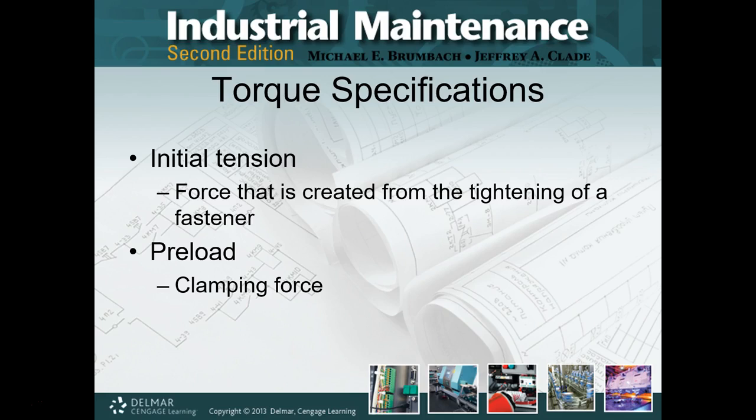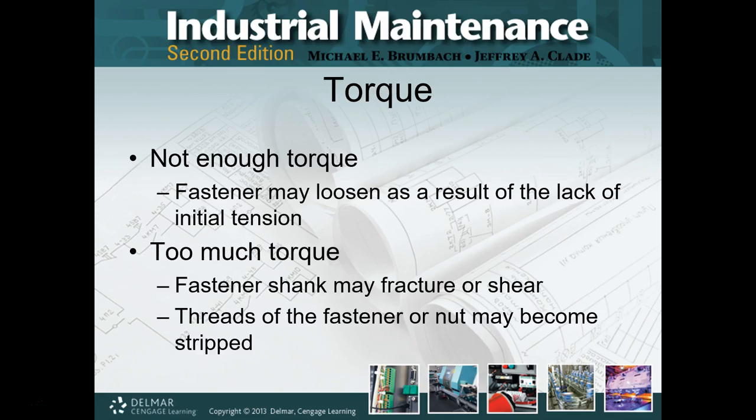The other place you'll see this is in some of the old railroad trestles, because that's easy to see. And if they're not using the hot rivets, they're going to still be using nuts and bolts, and those are also going to be tensioned either with initial tension or with the heating method, so we can make sure we've got the proper clamping force. All looking for the same deal. In worst case scenario, we can still use a torque wrench, and we can go from there.